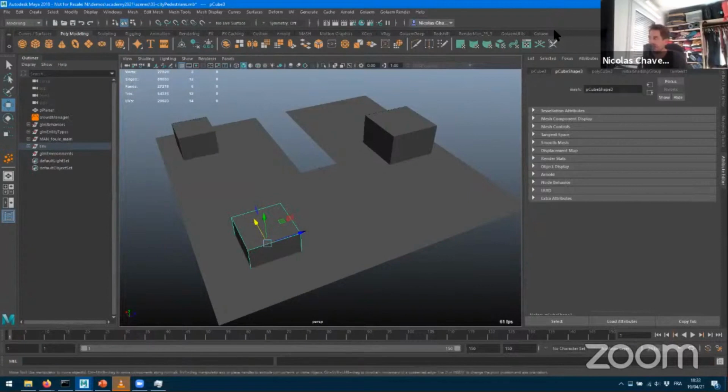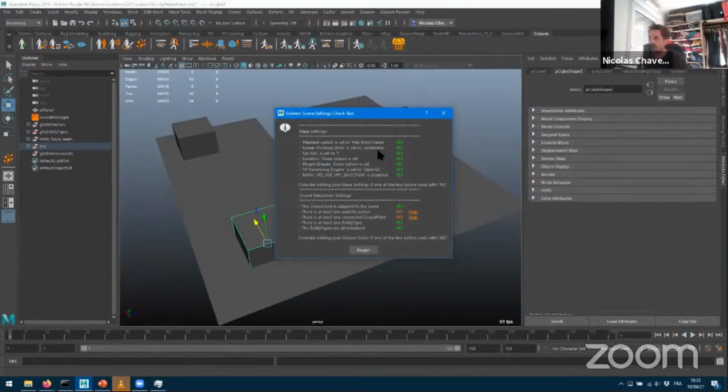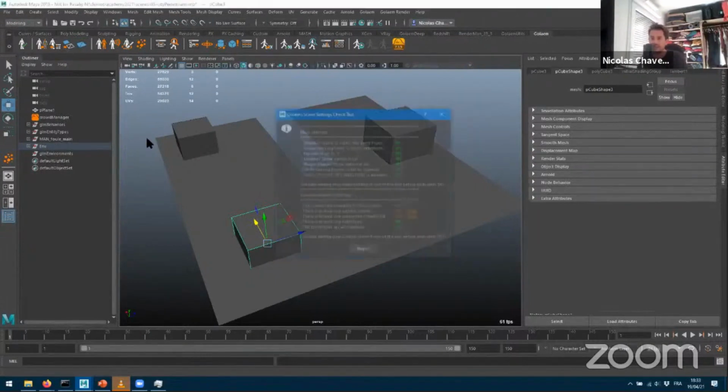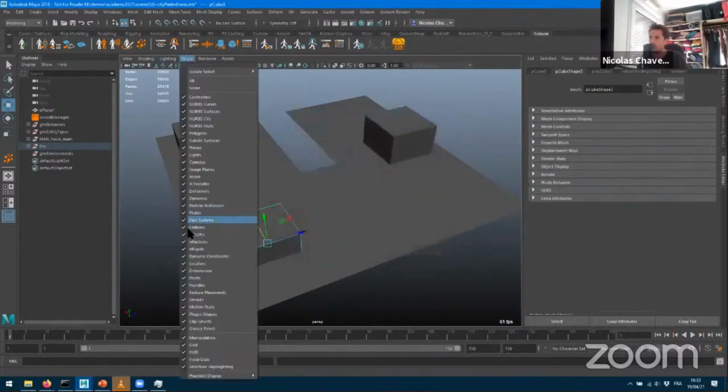Also, make sure that when you display Golaem here, when you use the settings, your locators are supposed to be shown, because terrain is using locators. If you really want to see what the terrain looks like in your scene, you want to make sure that the locators show option is set. One way to quickly check this is to use the check settings button to make sure that within the show options for your viewport, the locators option is enabled.